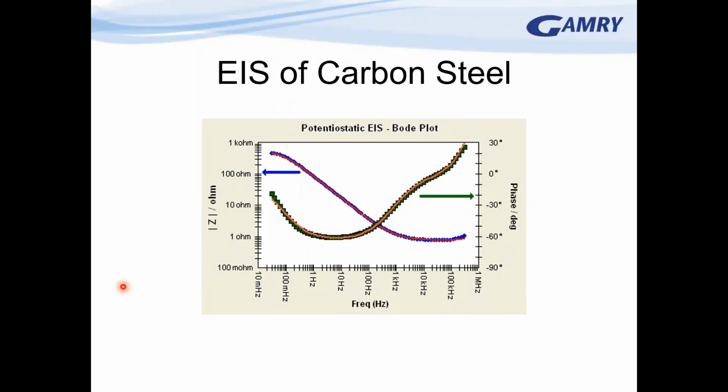Okay. Now let me see here, since we're still in this EIS of carbon steel, this is a more general question, but maybe we don't have the time. How do you model the EIS results to determine the corrosion rate of the alloy? So when you model any results, you've got to define the model, and the model has to have two inputs. One of them would be looking at the actual data to get an idea of what the model should be, and then the other one would be only adding modeling terms that relate to your understanding of the physical behavior of the surface.